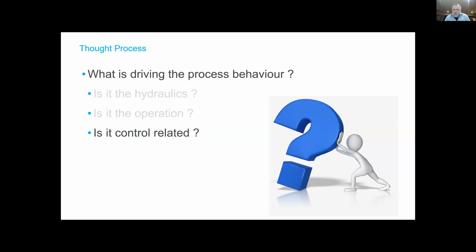I had a treatment plant a few years back where it was failing its ammonia consent every single day. And we went in and did a model, and the model clearly showed that there was a delay in the response of the aeration controller. And the owner of the plant swore up and down that there was no issue. And we said, well, I'm telling you that something weird is going on. They went and actually looked at the PLC code and found that there was a hard-coded 30-minute delay in the aeration controller. And I said to them, well, if you take that 30-minute delay out, I'm pretty sure your treatment plant will be fine. And sure enough, they took that out, and it was absolutely flatlined on ammonia. So these things do happen.